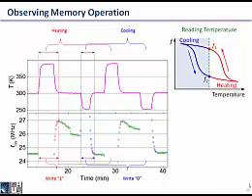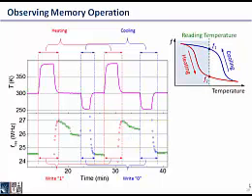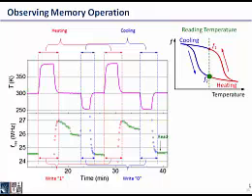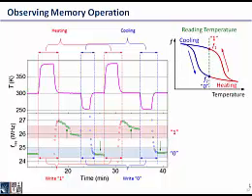Then I cool down the device and heat it back up, cool down the device, heat back up. And after that, I read the device frequency. It goes back to the lower frequency state. And I can continue: heat, and read. Found it goes to the high frequency state again, and I can cool again, and found it goes back to the other state. So basically, these two states can be viewed as 1 and 0, which correspond to the high frequency and the low frequency states.